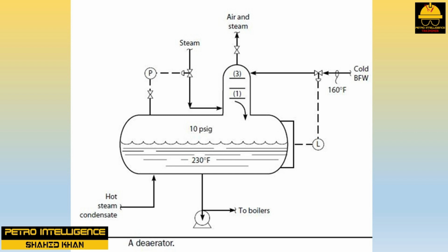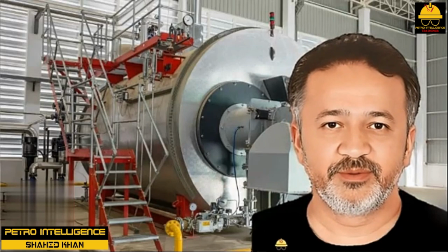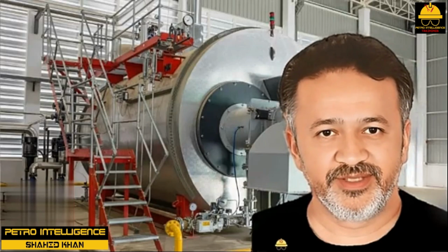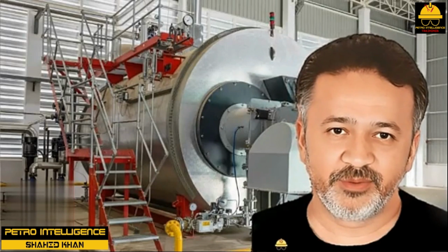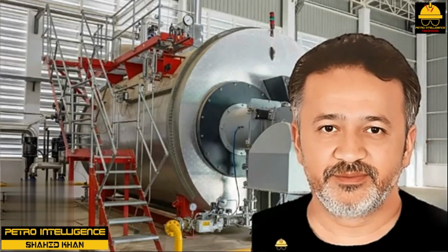He manually restricted the flow of cold BFW through the level control valve. This raised the stripper pressure and stopped the flooding. The problem was corrected by increasing the temperature of the cold BFW to 190 degrees Fahrenheit. Note that the key to solving this problem was observing the loss of water through the atmospheric vent. Sometimes, as far-fetched as an operator's description of a problem seems, it is still correct.